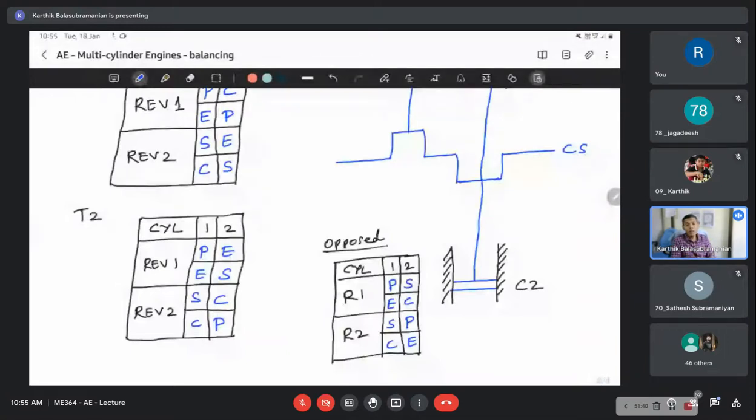So how does this enable holding the air inside? Because the moment the tube gets punctured in the tube tire, there is a gap between the rim and the valve, and the air escapes out through that. But whereas in a tubeless tire, since the valve is fixed on the rim, with any puncture on the tire, the only way air can leave the tire is through the tire hole only. There is no other way the air can escape.